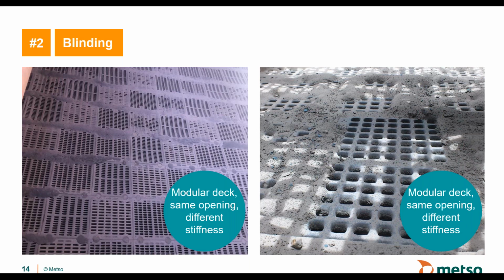That is actually because that area is above the support rails in the screen. So that area is firm. There's no flexibility in that area, and that's why you see more blinding above the rails. But if you look in the aperture area, there are different degrees of blinding, as we mentioned. Some panels are completely without blinding, and some panels have more than half of it blinded.